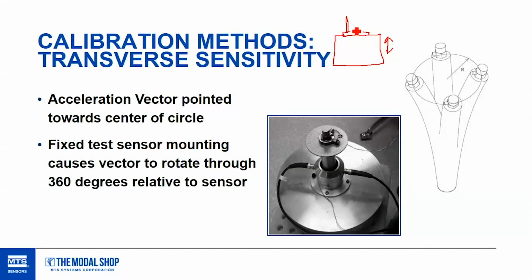Rather than putting the sensor on the shaker aligned with that axis of motion, we can just place the sensor on the upright perpendicular. So we'll put our sensor on there and attach a little connector to it. As you can imagine, this sensor is designed to measure, in the case of this page, left and right. So if we put it on that shaker, we can shake it and measure across the left and right of this accelerometer. And that works pretty well for that one measurement.